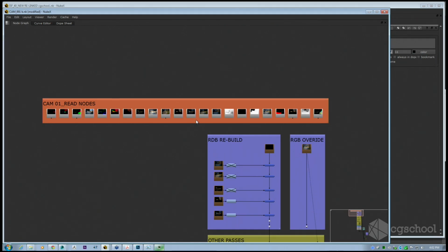And then what we've started to do is set this up as almost like a batch command, but using Max and Nuke, where we've gone to extreme referencing. We have all of the model files referenced into a cam lighting file, and in that cam lighting file you've just got your lighting and your cameras as you would normally, but then that file is referenced into a render send file, right? The render send file has nothing in it apart from an area to send your render, and then you can send that to Backburner or whatever system you're using.